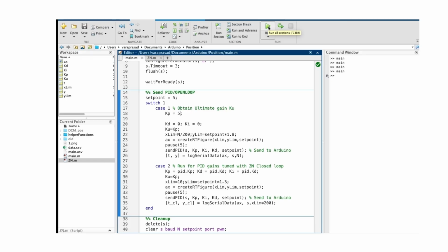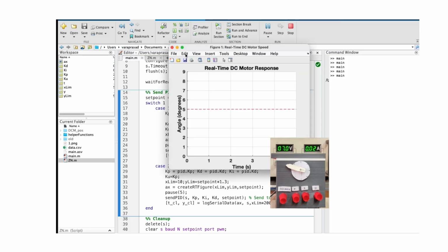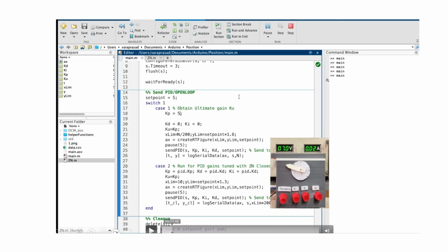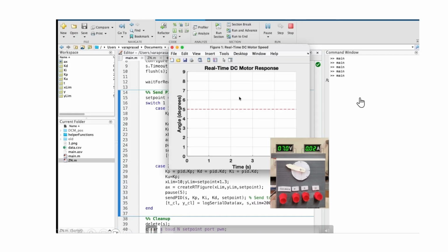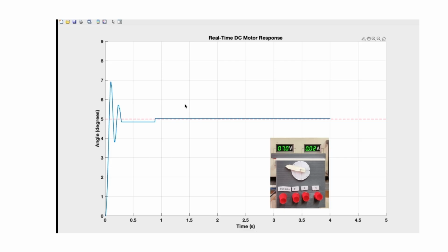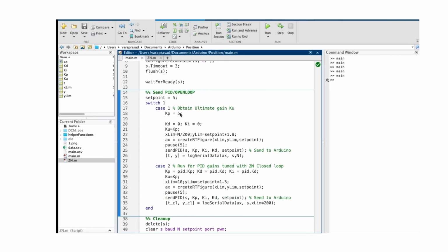The hardware setup is similar to what we discussed for the open loop case. So, there is no change there. Only thing is that now we have the controller in the loop, and you can see that in this closed loop setup where your k value, the gain value, was 5, this is the output. You can see that the shaft of the motor rotates a bit and then stops, because this is position control. So, basically we are saying that the shaft of the motor has to go to a particular point and then it has to stop there, and you can see that it does that.